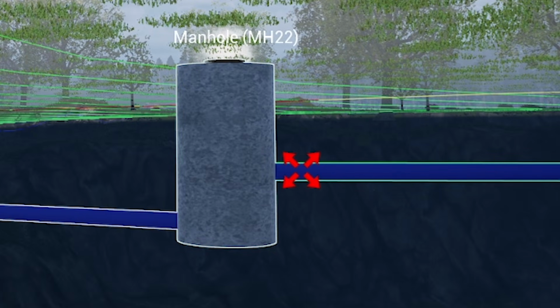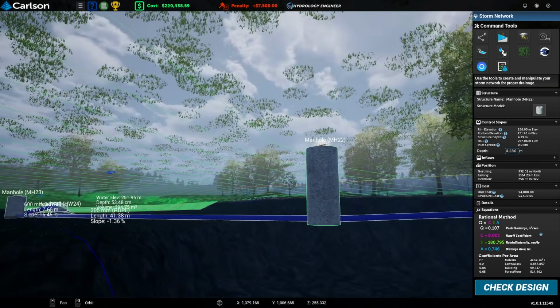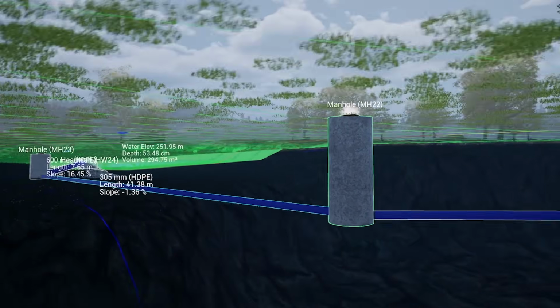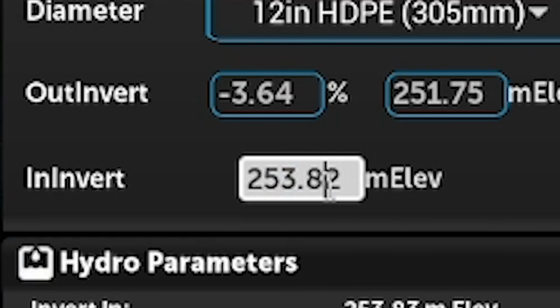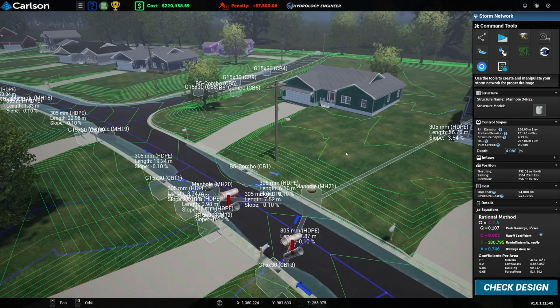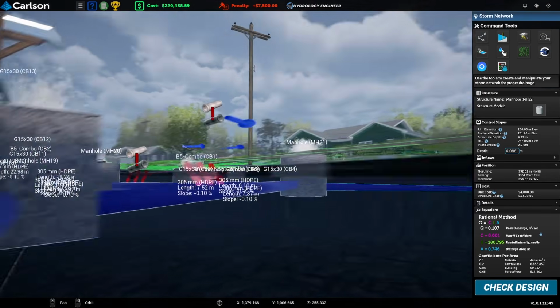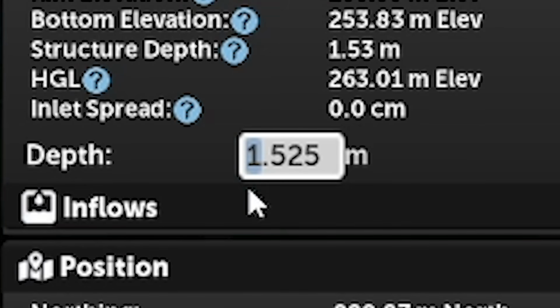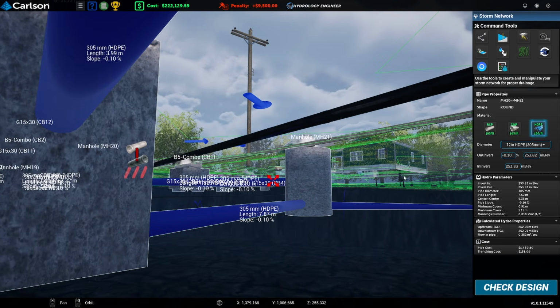So I want to lower that pipe by 2 meters as well. So if I just make that elevation a 1, then nice. That's much deeper. Although actually, I think that's deep. Yeah, that's deeper than the pond. So we have to bring this up a little bit. Let's bring it up by, I don't know, 500 mil. If we make that a 3 and that a 4, then that should be good. It means the upstream manhole here, we can now lower this because that pipe's really, really steep. So if we lower that by, I mean, we could do a meter. So you can see I'm just lowering all the pipes coming into it by a meter. So rather than a 3 there, that's the invert level, by the way.